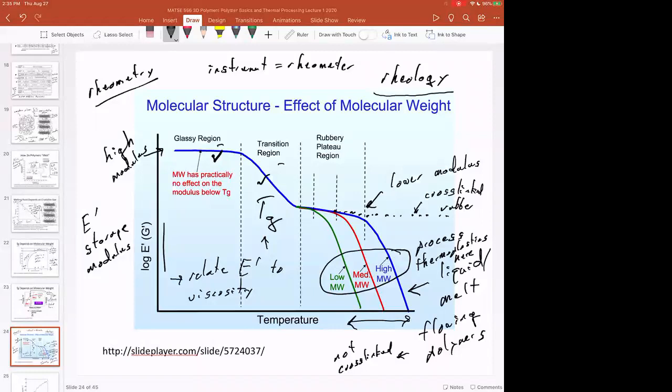It's really hard to fuse two super balls together, right? They're cross-linked, they don't want to fuse, you can try and jam them together, nothing happens. But if you wait long enough, you can fuse two balls of silly putty together. And so you can slowly squish them together. Of course, they bounce off one another if the time scale is too short. We'll talk about the time scale part of this in a second. But you really need to have low viscosity to get good fusion.